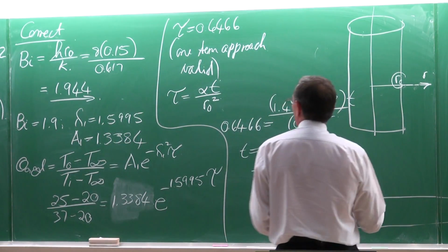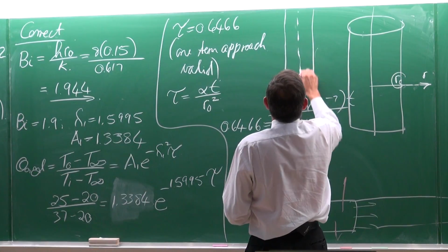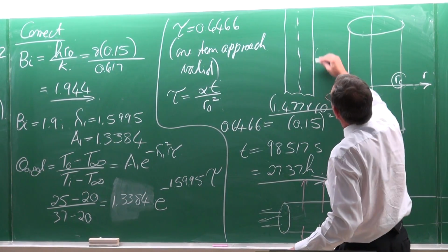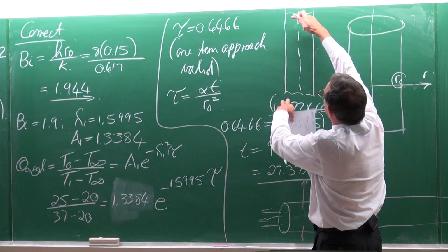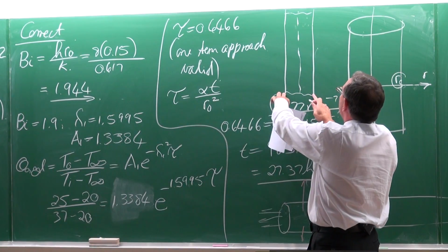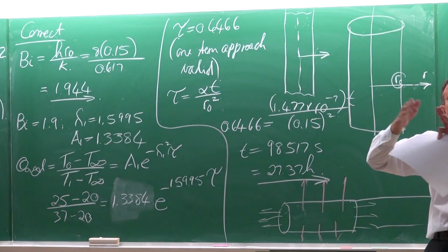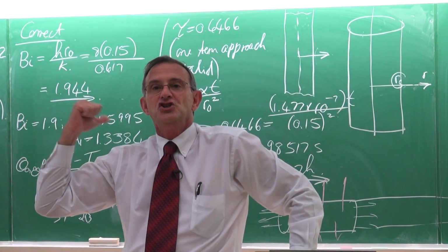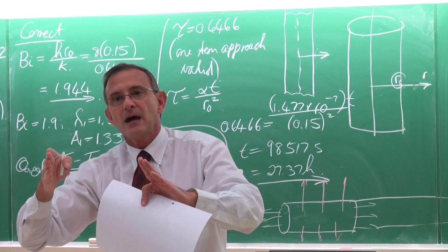When we solved, firstly, the large plane wall, it was a wall which was considered as very long. So this distance is very long in comparison with this, and therefore it was a good assumption to say that the heat transfer rate is in one dimension only. So when we considered the energy equation, we said heat transfer rate is in the x direction.